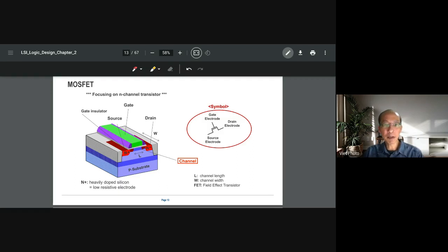In reality, there will be something else here, like the N well, but here they present a simple thing so that you can get a concept about that. So we have this N transistor. It means the drain and source here are N plus. Then in between, the distance between these two is called the gate length, which is L. This gate length, and the gate here, they will apply the voltage here. They have a voltage applied to these two.